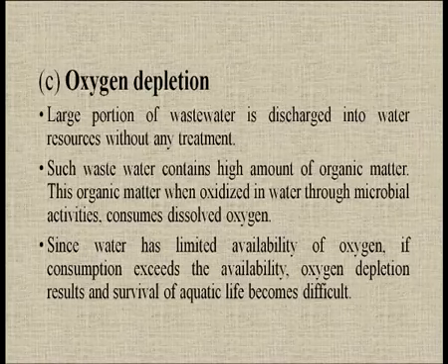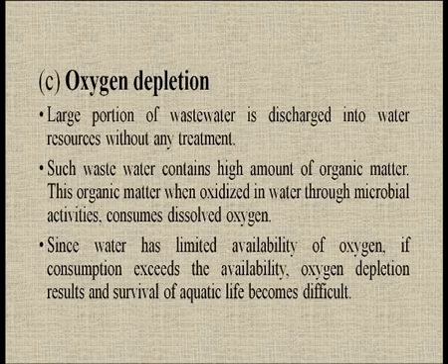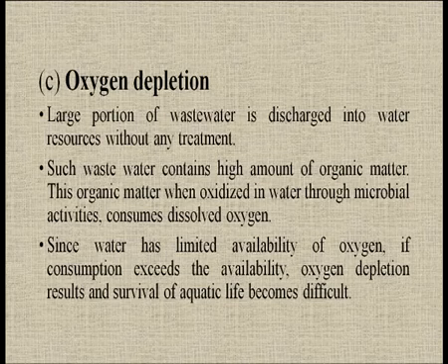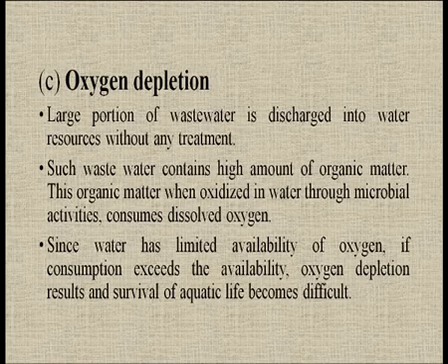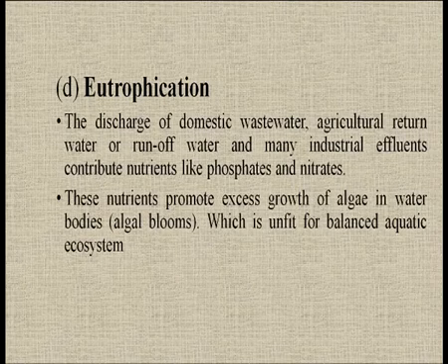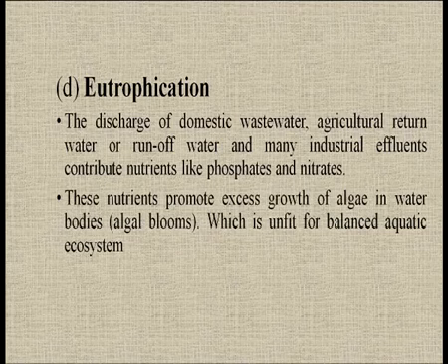A large portion of wastewater is discharged into water resources without any treatment. Such wastewater contains a high amount of organic matter. This organic matter, when oxidized in water through microbial activities, consumes dissolved oxygen. Since water has limited availability of oxygen, if consumption exceeds the availability, oxygen depletion results and survival of aquatic life becomes difficult. Eutrophication.